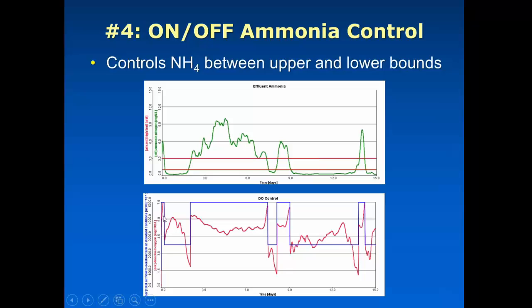And you can see that the in blue here, the airflow, it spends some time at the lower limit and at the upper limit. Those are the only two values that will ever be in an on-off controller, or a high-low controller. So it's sort of doing the best job that it can. It just keeps monitoring whether this value is above those limits or below them.